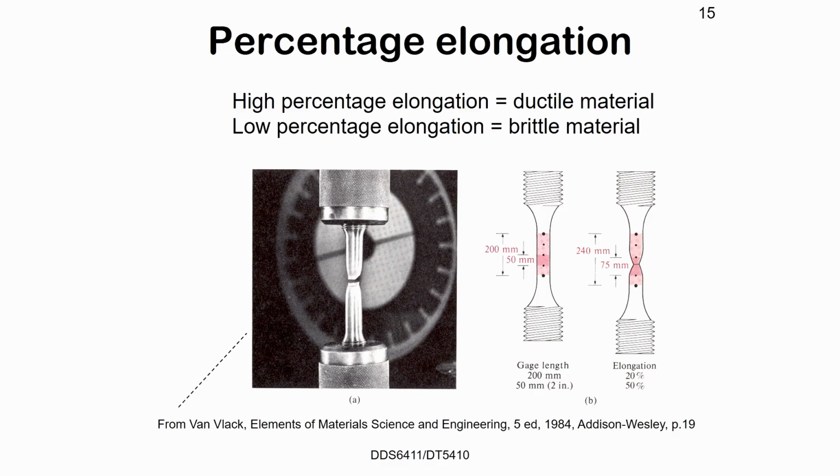When you were talking about the ultimate strength, you're saying this one is higher than the maximum strength because if the area was the same, it would be linear? That's necking. Because the cross-sectional area reduces, the actual stress, the real stress, would be much higher than what is depicted. What is depicted was calculated using the original cross-section. Okay, that makes sense.